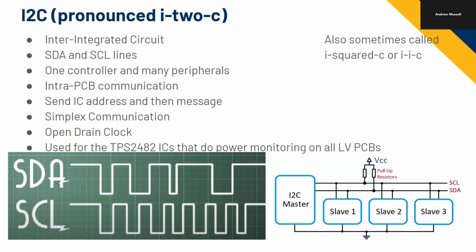Then on your PCB, you might have a higher speed communication that is coupling to this communication. If you remember, we talked about circuit fundamentals last week. Every piece of copper sort of makes a capacitor with every other piece of copper in your board. The impedance of a capacitor reduces with frequency, so a higher speed communication will couple to that lower communication and might add more frequencies on top of it.